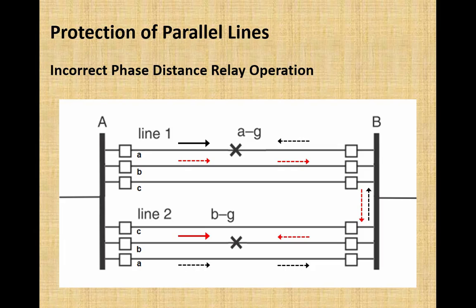So there is confusion in post fault analysis. What was the reason for tripping of the line? It is due to the cross country fault, where a fault produced in one phase of one line has extended to the second line, and their simultaneous existence has converted the line to ground fault into a line to line fault, and that would result in misjudgment of the fault.